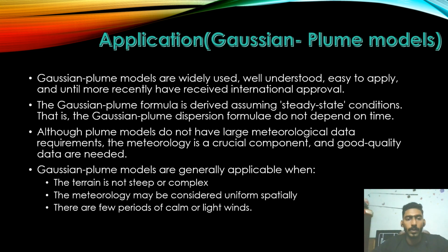As we see for the applications of Gaussian-Plume models, Gaussian-Plume models are widely used, well understood, easy to apply, and until more recently have received international approval. The Gaussian-Plume formula is derived assuming steady-state conditions. That is, the Gaussian-Plume dispersion formula does not depend on time.